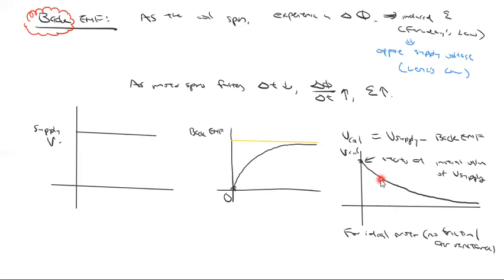The other way they could ask the question, it's all the same question, is: why do you need a starting resistor in a motor? The reason is that without a starting resistor, you're going to have a very high current from a very high voltage. The motor's not going to be at this stage for very long.